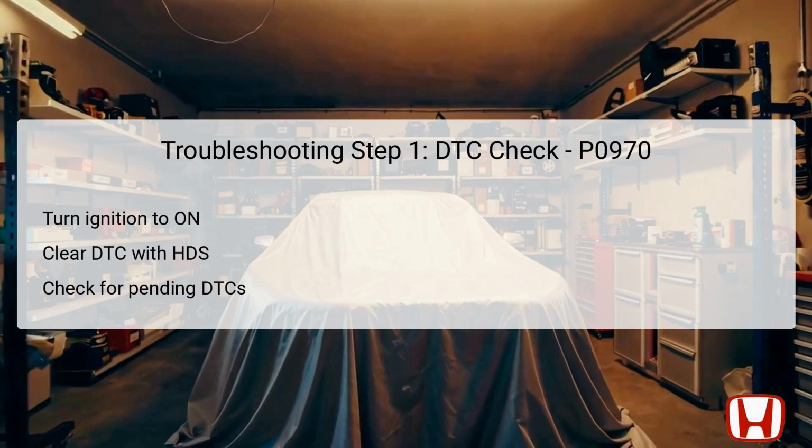The first step in troubleshooting DTC P0970 is to verify the existence of the trouble code. Begin by turning the ignition switch to the on position, which powers up the vehicle's electronic systems. Next, clear the DTC using the HDS, Honda Diagnostic System, to reset the error codes recorded in the PCM. After clearing, start the engine and allow it to run for at least 1 second to enable the system to reevaluate its parameters.